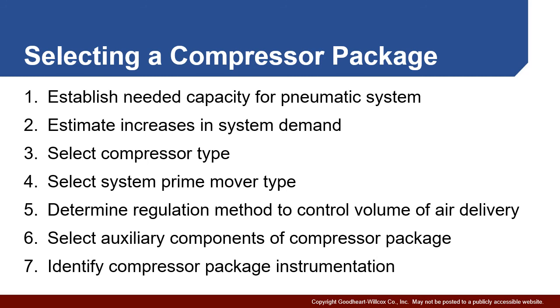Lastly, I should say, then look at your auxiliary components. Clearly, you're going to need various filters. If you're talking about any kind of high efficiency precision equipment, you're going to need dryers, and you're going to need coolers to get the air in at the right set of properties, right condition. And then last, what type of instrumentation are you going to use? Again, that's tied back to your regulation method. It's also tied to the equipment you have available. If you already have some sort of industrial automation system, you might want to tie it into that. So a bunch of choices there.